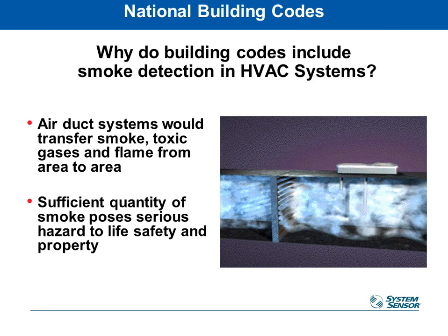Air duct systems are a great transfer media to move the smoke around the building and also provide fresh oxygen to fires. So we definitely want to shut down the fan systems in the event of a smoke or fire condition so we don't continue to move all that smoke around the building.